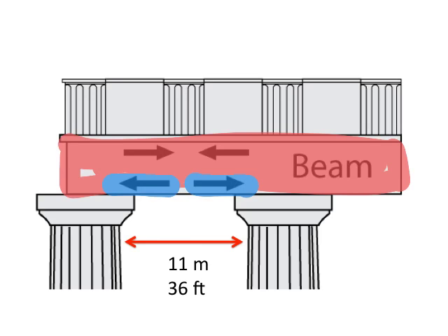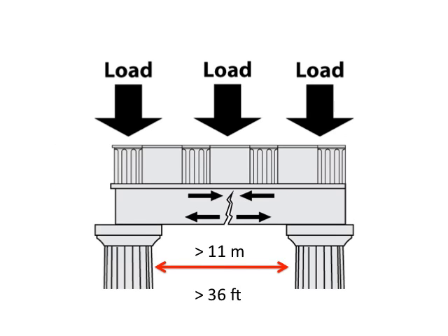And this is what's going to happen. What's going to happen is it's going to crack. Remember, at the bottom of the beam is where tension is happening. And stone is extremely weak in tension. So it's going to crack there, and then the whole thing is just going to collapse.